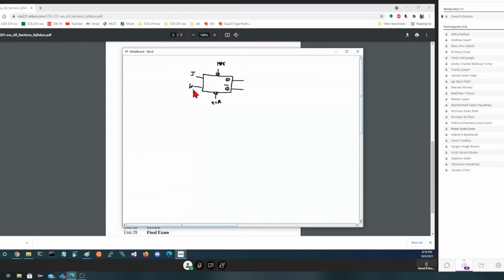Now, if it's a flip-flop, there's going to be an edge-triggered clock. Clocks generally are drawn either below the first input. In case of a T, there'd only be one input, or a D. And the clock appears as a signal here, maybe labeled inside or outside. We'll put it out here this time. And if it's labeled just like this, pressed up against the box, it's a level clock. If it has an inverter on it, or the name is overbarred, or both, normally it's an inverted clock, meaning that the level is when it's low, not when it's high.